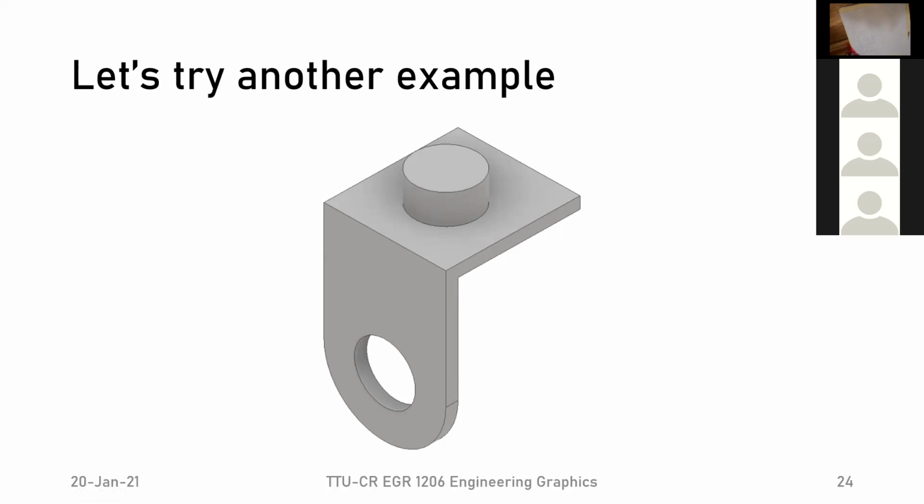Like this. And now there's one more set of hidden lines that we have to do. If we imagine that we're looking down on this part right here, looking straight down along this flange that's going downward, then that means we need to be able to see where the edges of this circle are. If we're looking down along this piece, we go down to where our circle is, right here, and then we can put our ruler and say we have to have a hidden line right here. And the same on the other side. These now represent the edge of the circle.